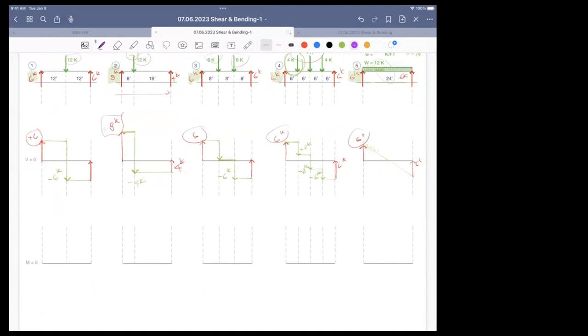Okay. Let's do the following. The next thing we need to do is figure out, forget that. I need to recognize this point, because the areas are going from plus to minus, so areas are changing. Please, the moment diagram is the sum of areas in the shear diagram. That's why I'm starting to look at the shear diagram and examining it. I have 0 shear with areas going from plus to minus.